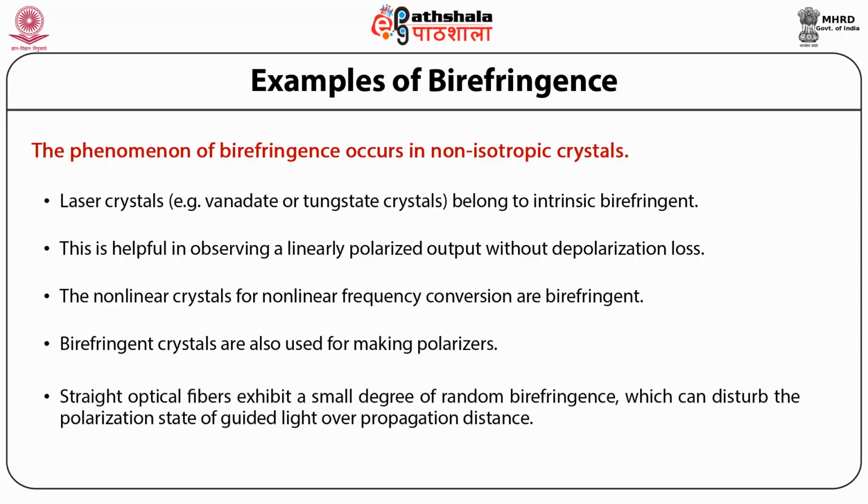Straight optical fibers exhibit a small degree of random birefringence which can disturb the polarization state of guided light over propagation distance. There are polarization maintaining fibers with strong artificial birefringence, which are used for suppressing such effects.